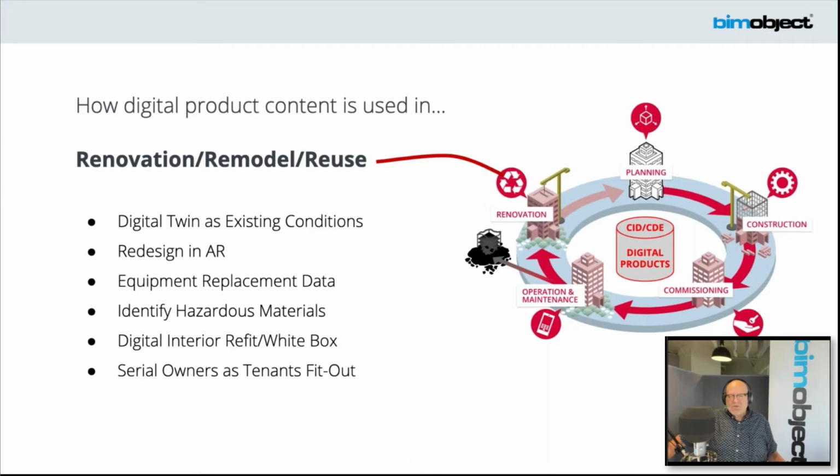So augmented reality means that you do see the environment you're walking around in with a set of glasses, like wearing sunglasses. There are all different form factors and devices. And on those, there's a scene imposed of the future, what's going to be done. We've even seen that used in the construction phase for metal stud framing, where trade contractors are actually using these devices, though the form factor I wouldn't suggest is optimum yet. They are able to completely frame complete fit-outs without really using a tape measure and chalk lines to lay it out, because it's all imposed in the space.